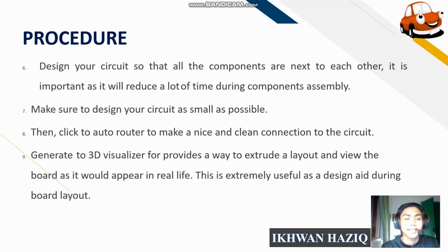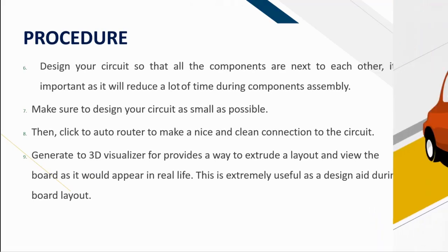And for the next, we make sure to design the circuit as small as we can, to make sure the PCB can be fixed, and then use the autorouter to make a nice and clean connection to the circuit. And next, we generate the 3D visualizer, which provides a way to extrude the layout and view the board as it will appear in real life. This is extremely useful during the board layout design.